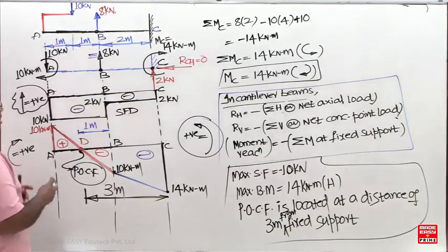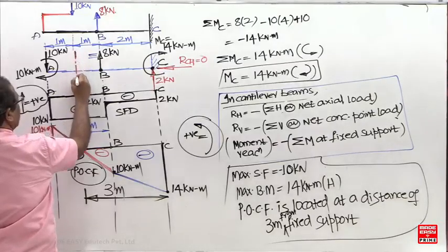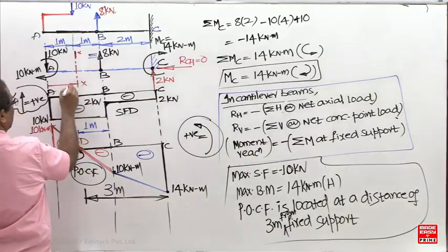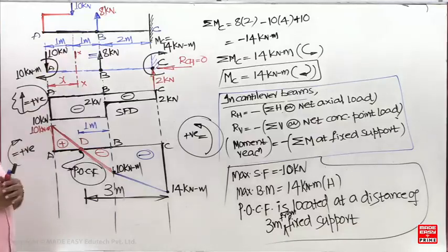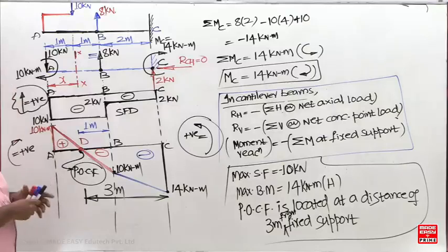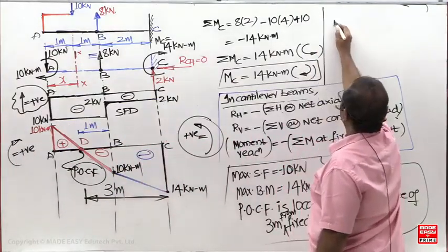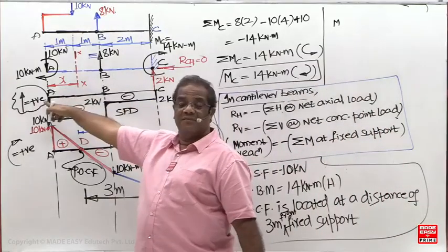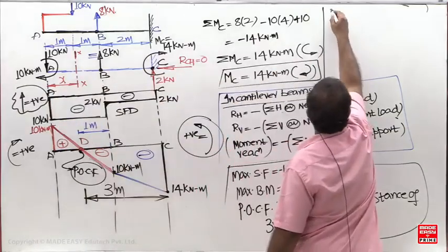Sir, I want to cross check my calculation, then you can check it now. Better to consider left side or right side? Left side you consider now. Can you write down the bending moment equation now? It is changing sign between A and B. Take a section, write down the bending moment equation. I have taken a section between A and B. So x is taken from the left side. So what are the limits now? x is equal to 0 to 2.